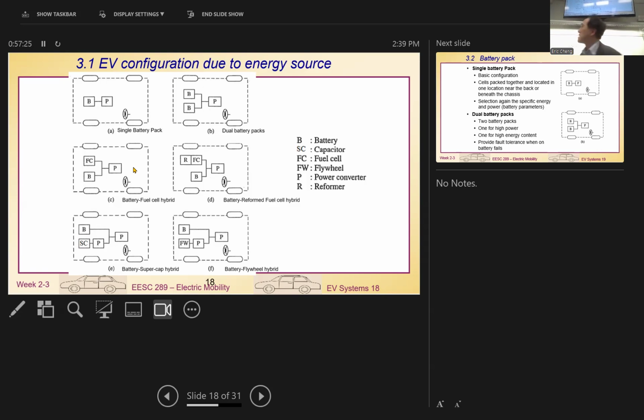But having said that, nowadays all the battery design will be, as you see in the last picture I showed you last week, a large surface of battery at the bottom of the car in the chassis. But still they connect all of them together in a single 800 volt. But if one of the cells is broken, will that 800 volt not work? Depending on the design, they may have some bypass. The 800 volt may become 790, still good.